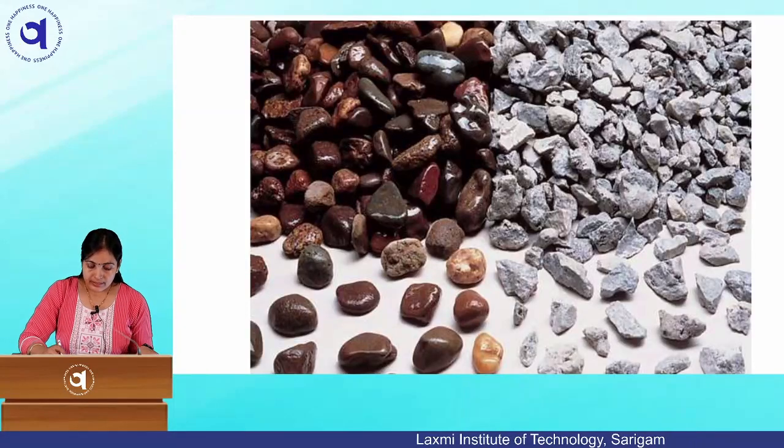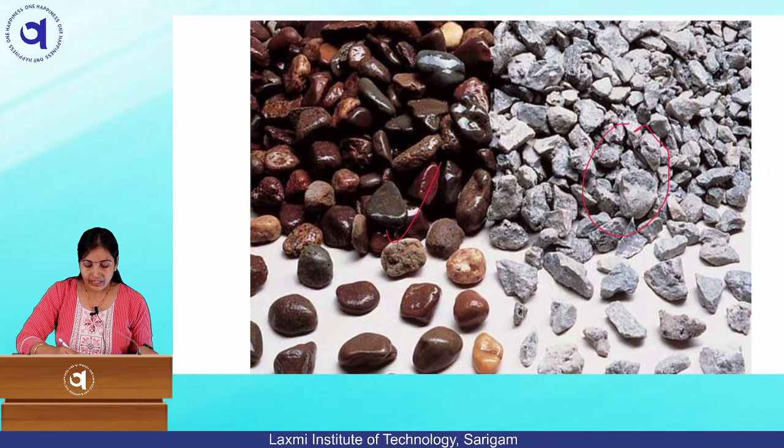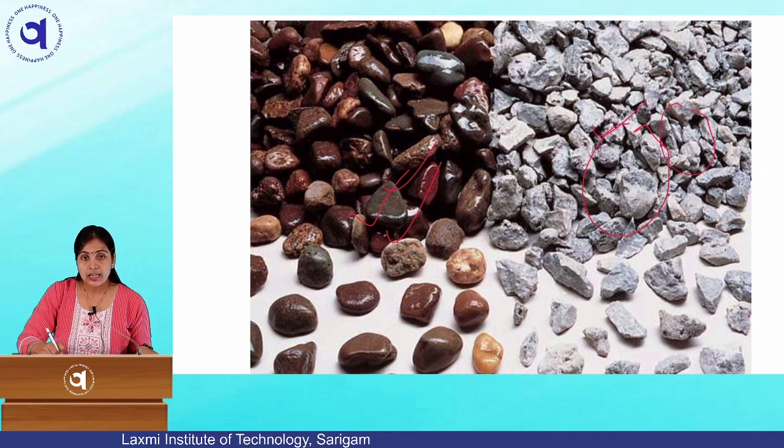Here we have coarse aggregate, which can vary from angular aggregate to rounded aggregate. You can see this one has a glassy type of surface, and it helps in the workability of the concrete. But this one has a rough surface and is angular aggregate, and this helps in creating a bond with the concrete. It acts as more binding than the other aggregate.